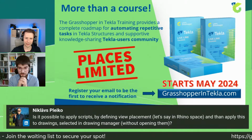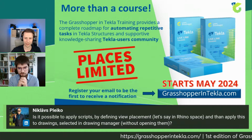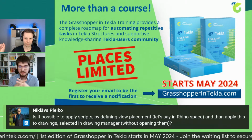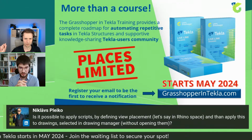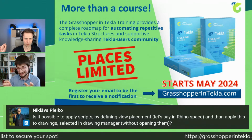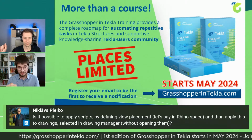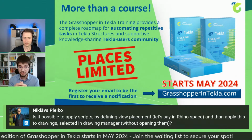Niklavas asks, is it possible to apply scripts by defining view placement, let's say in Rhino space, and then apply to drawings, like selecting in Drawing Manager without opening them? I will start from the end because it's much easier. You can't fully manipulate the drawing space without opening the drawing. You can open the drawing in a hidden mode, so as a user you will not see the black screen of Tekla and all of those drawing objects, but it has to be opened in the background. And of course, opening it in the hidden mode is much faster than fully rendering those objects.